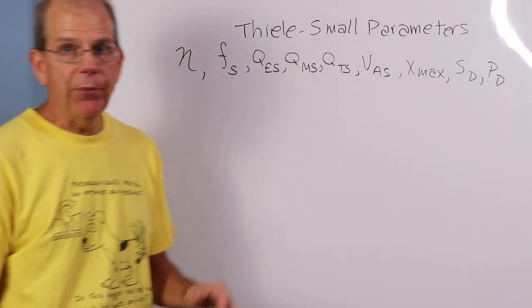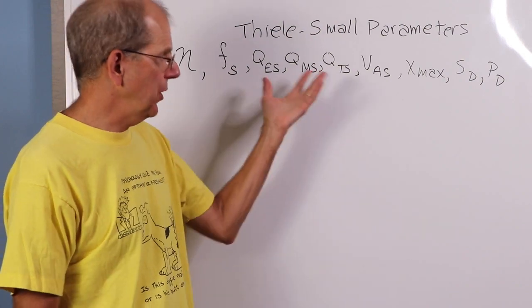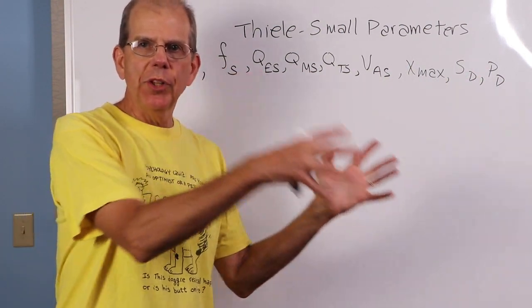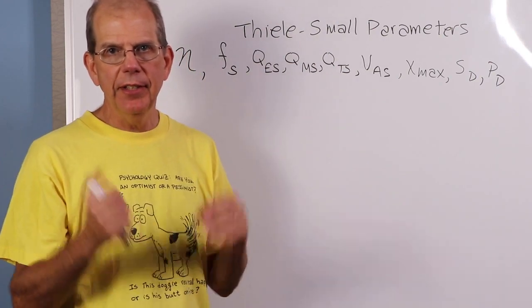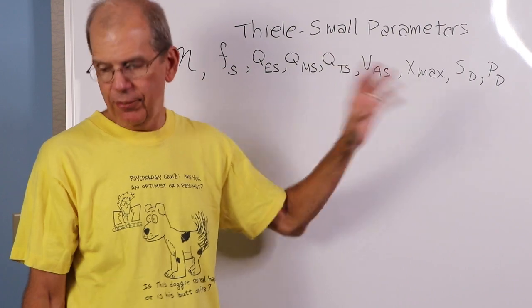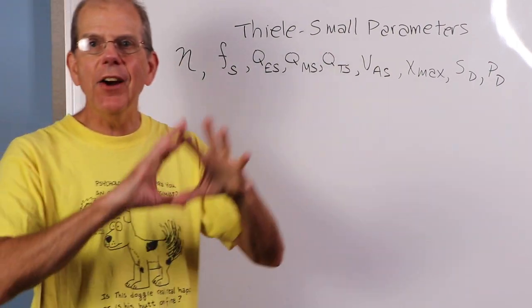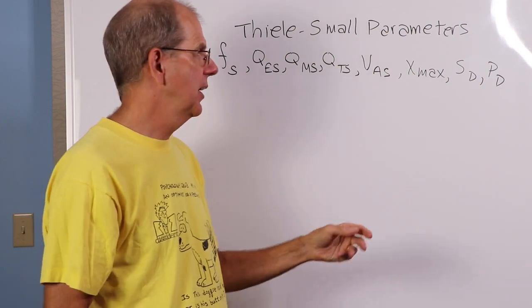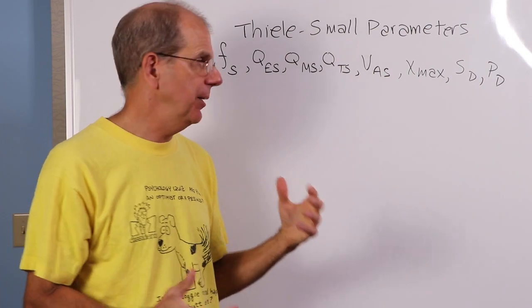So even if you have something that is fairly efficient and you've got a decent power, once we get into really low frequencies, the limiting factor is going to be the X max. That's on the large signal limit, as we call it, when the thing is really moving, when we start talking about mechanical limits.